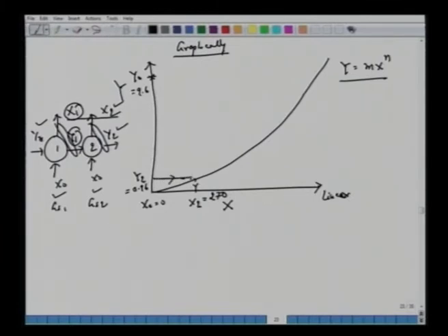Alright, now how do we get GS1, GS2 and y1? We do not know the slope. For cross current it's a negative slope of GS1 over LS, so all it means is it requires iterations. So let's take an arbitrary line like this. That means we have assumed a certain slope, or we have assumed a certain amount of solid. So essentially we have negative slope GS1 over LS here, and when we reach this, so that's your y0, this is brought down to y1. So this would be your value of y1 here, corresponding to which you will get x1.